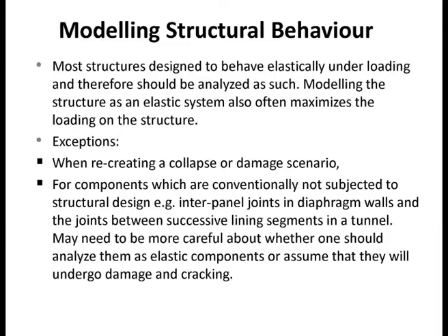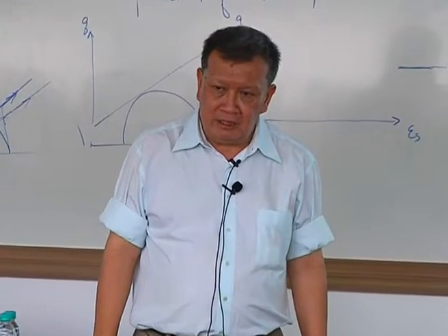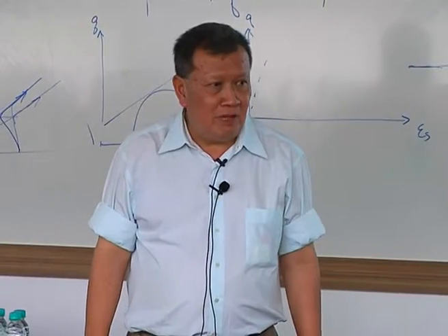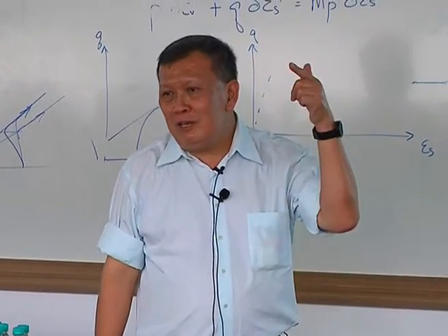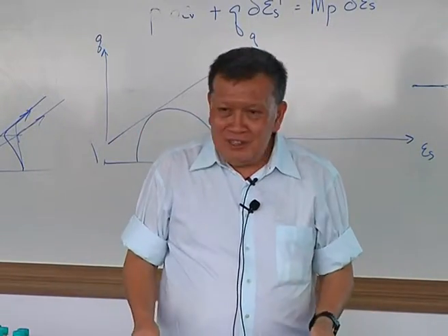Similarly with the linings in tunnels, the segmental linings, very often the linings are designed so that the steel reinforcement is circumferential. And there may be a few rebars, starter bars going out, but not too many. So when I ask tunneling engineers, I say, what is the longitudinal stiffness of your lining? The usual answer is, actually I don't know, because we never calculate it. It's just for continuity purposes. The lining is supposed to stand up just like that, so I don't bother to calculate.